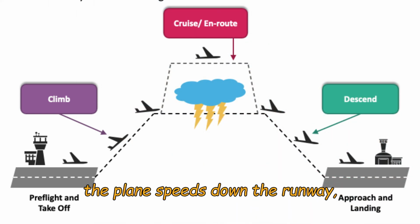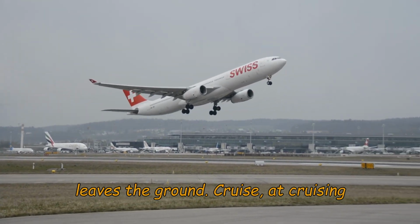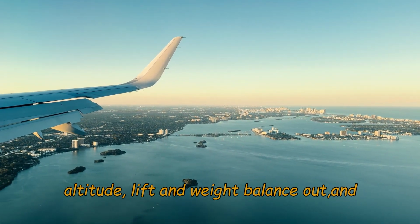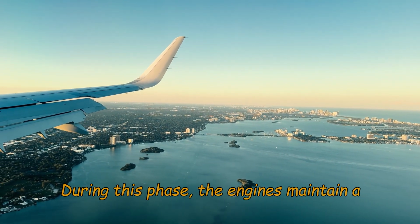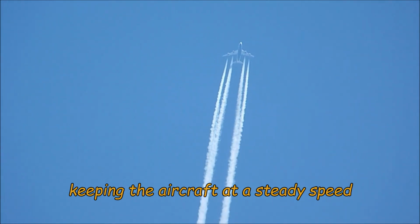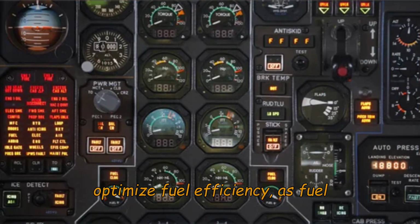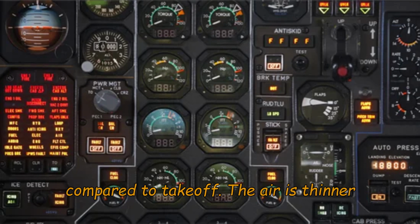Takeoff. The plane speeds down the runway, increasing thrust and lift until it leaves the ground. Cruise. At cruising altitude, lift and weight balance out, and the plane moves smoothly through the air. During this phase, the engines maintain a constant thrust to overcome drag, while keeping the aircraft at a steady speed and altitude. Pilots adjust controls to optimize fuel efficiency, as fuel consumption is lower in this phase compared to takeoff.